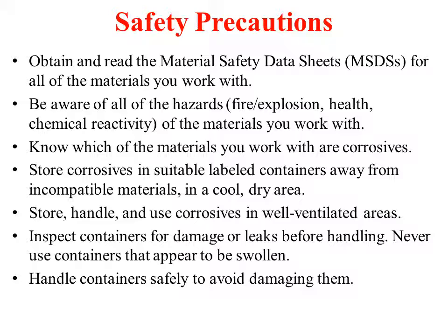Store, handle, and use corrosives in well ventilated areas. Very important. So whenever these containers containing chemicals are stored, there should be proper ventilation. There should be a well designed and well maintained ventilation system, so that if there are any chances of spillage, and any chances of corrosive vapors or fumes or mist or airborne dust, they should be properly moved out.